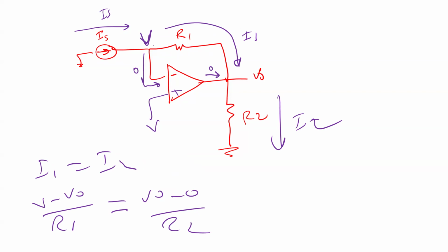You got what I'm saying? If the current here is 0, yes, what you did is correct, but this current is not 0. And I don't have a way to calculate it. If I want to calculate this current, I need to calculate I1 first, then I2, and then apply Kirchhoff's current law. But there is a current here. So it is true to say this current equals this current here, but it is not true here because this current is not 0. The currents into the op-amp inputs are 0. I found some students made this mistake. Anyway,